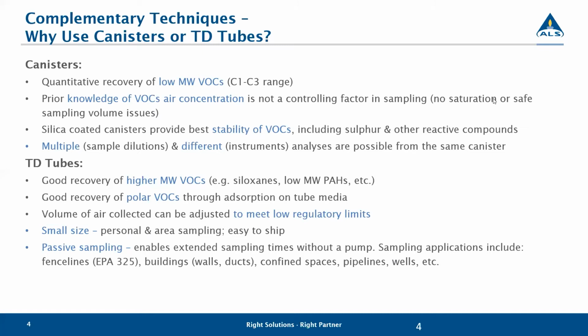So what we do when we get it in, again, we do the leak check on the canister. We will then add as much nitrogen as we need to, and we keep this to a minimum because we want to keep the dilutions down as it requires to be able to run that sample. So I can give you, and I'm happy to provide this for any of you that are interested in this calculation going forward. But when a sample comes to us at -22 inches of mercury, that works out to about 3.9 psi. When we put this all through